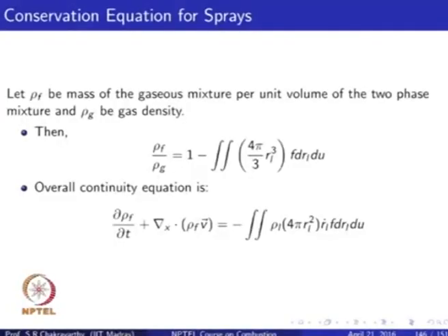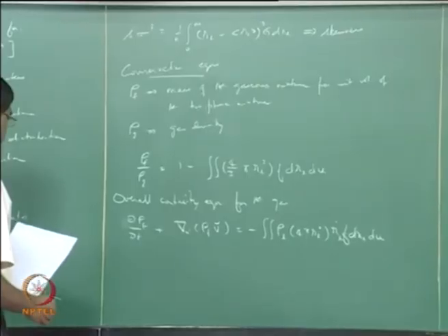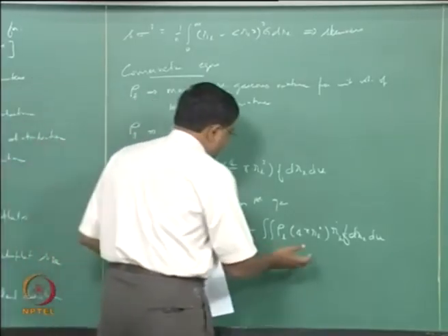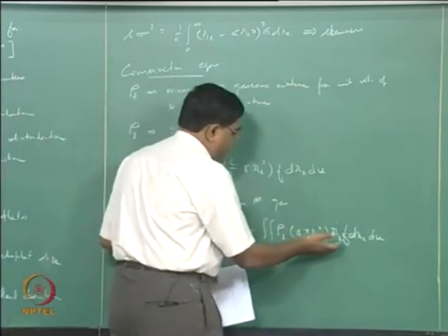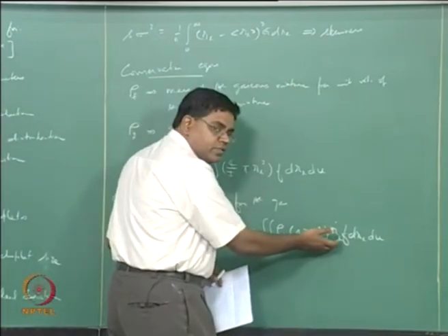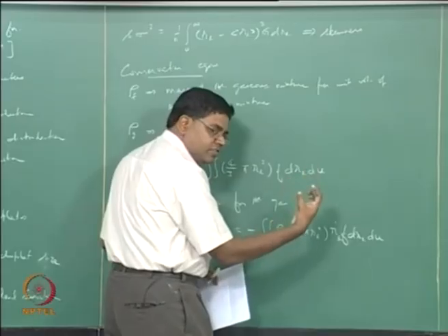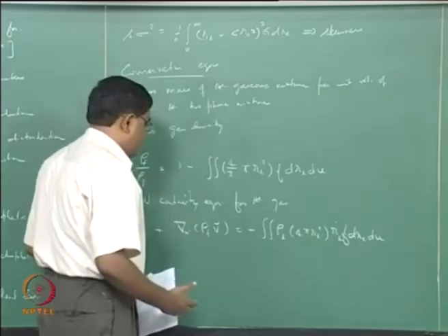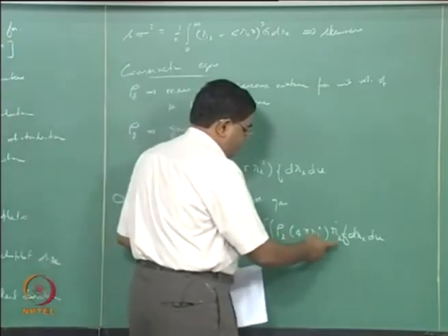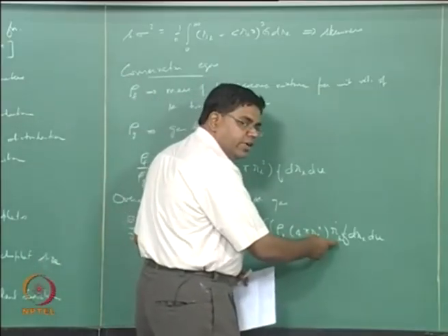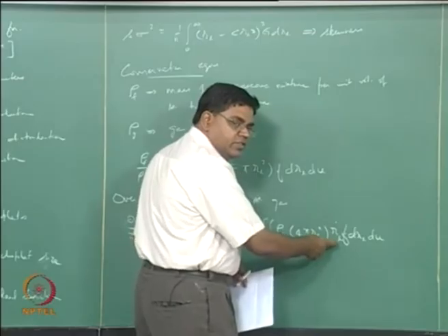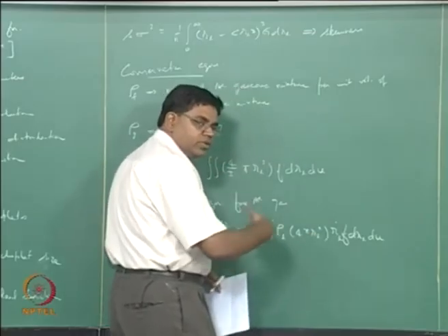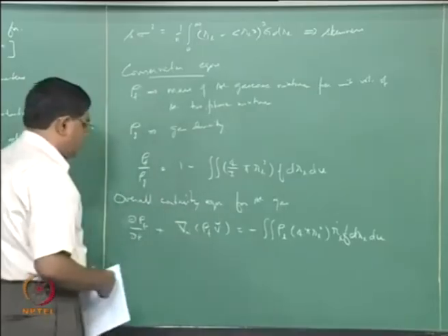So here what's going on is, this is basically the rate at which the liquid evaporates or its surface regresses and then produces gas, right. Since this is dRL by dt, where RL decreases as time increases, you need a negative quantity to make sure that you're adding mass to the gas.